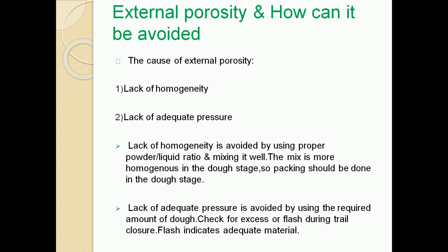Before coming on to the crazing, I have some important questions regarding the porosity. First MCQ: if curing occurs at a temperature more than 100 degrees Celsius, porosity occurs at, answer is the thick, central area. I repeat, if curing occurs at a temperature more than 100 degrees Celsius, porosity occurs at, answer is the thick, central area of the denture.